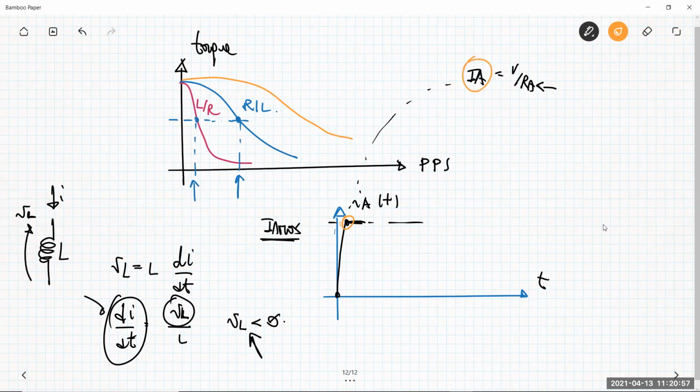and at the turn off applying the highest possible value of the negative voltage across the inductor to speed up this turn off. Okay, these are basically the two situations that I want to exploit for another circuit, which is called the chopper drive for stepper motor. Okay, that I explain tomorrow.